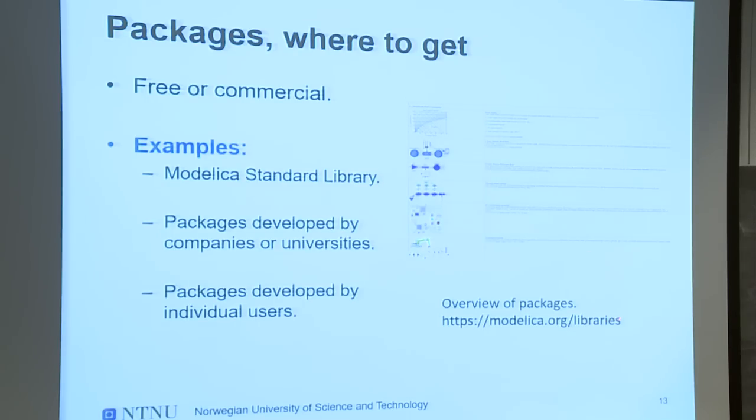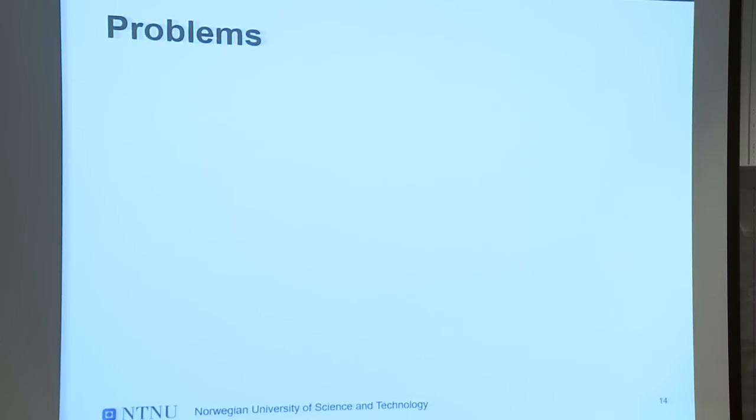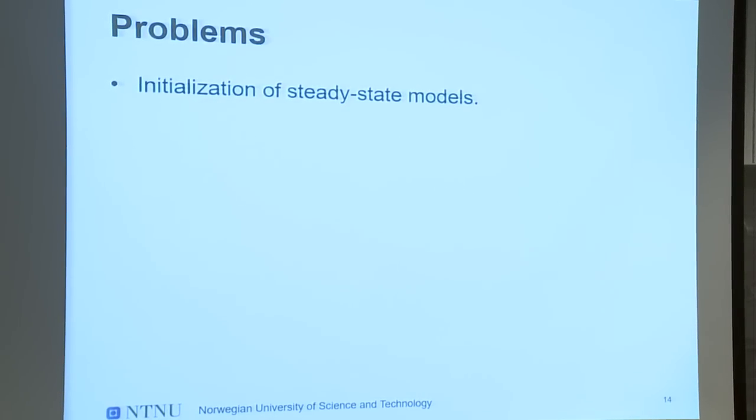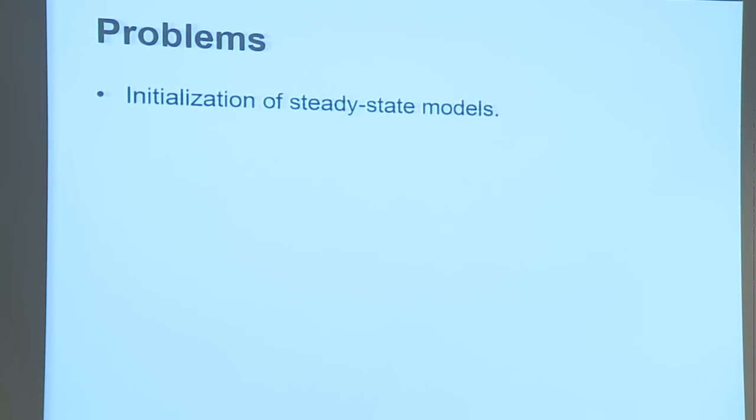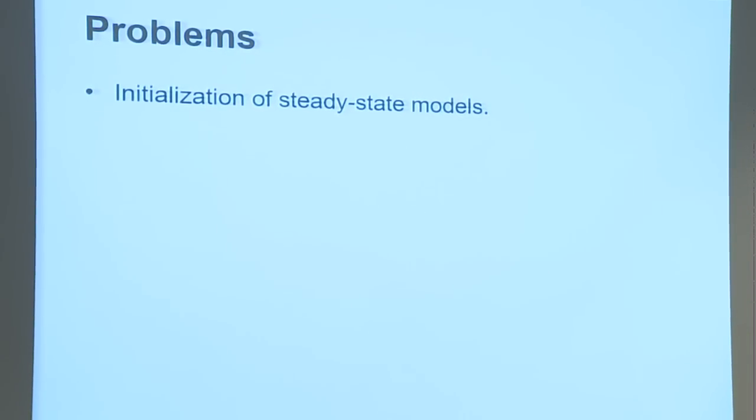There is a really nice overview of packages on the Modelica webpage. When the presentation is uploaded, you will have the link. That makes it way easier. As nice as Dymola and Modelica sound, there are some problems. I have encountered a few problems during my time with it, and sometimes it was quite nasty. If you have steady state models, non-dynamic models, you can use Dymola perfectly to model them. However, the initialization is quite nasty.